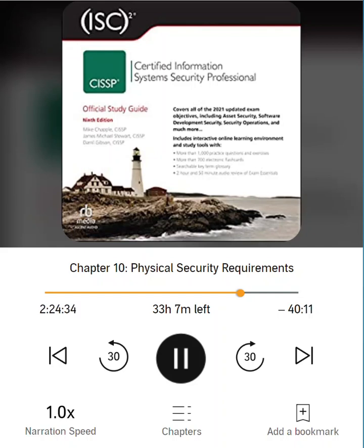Know about static electricity. Even on non-static carpeting, if the environment has low humidity, it is still possible to generate 20,000-volt static discharges. Even minimal levels of static discharge can destroy electronic equipment.